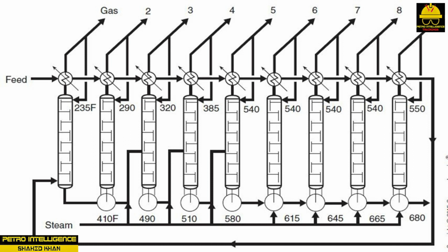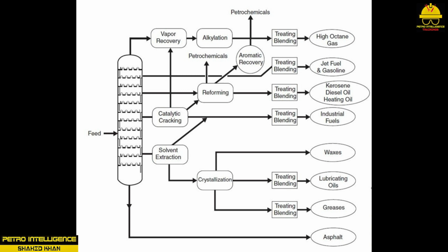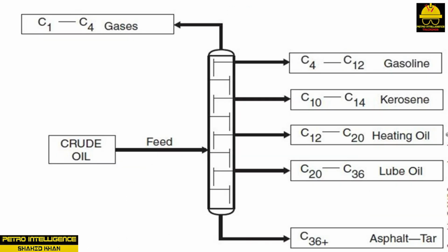Modern fractional distillation, as shown in picture, uses a series of trays or packing inside a tower. A continuous feed is heated and fed to the distillation column. Hot vapors rise in the column while liquids drop down the tower. A series of steps involving vaporization and condensation take place inside the column. Vapor-liquid contact allows the heavier molecules to drop out and the small, lighter molecules to rise up the column. The various fractions are separated by their individual boiling points and distributed on the trays. Product purification is enhanced by the still-upon-still approach, as shown in picture.